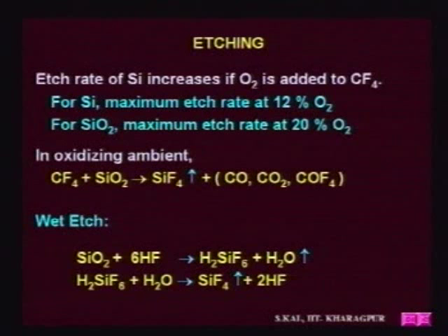That is not true in case of the dry etching process, because there the gases are continuously poured through the inlet, and through the outlet the gas is taken out. So, a continuous flow is maintained into the chamber, and the wafer always faces fresh gas. In wet etching, on the other hand, the etch byproduct can dilute the etchant molecules. So, that is one of the differences between wet and dry etch processes.